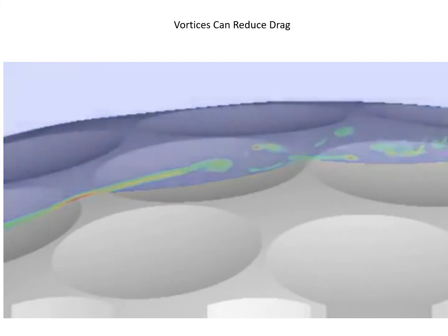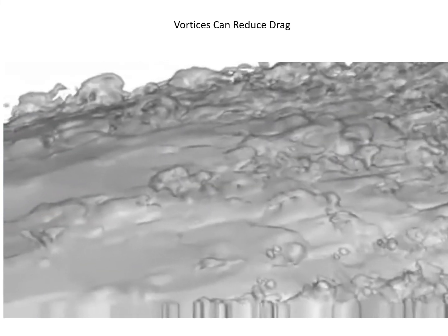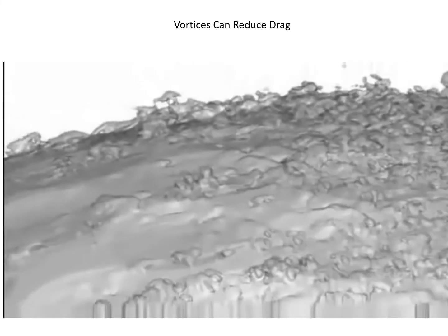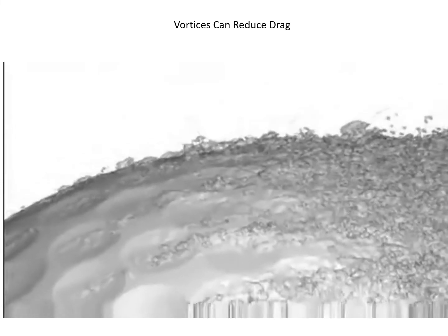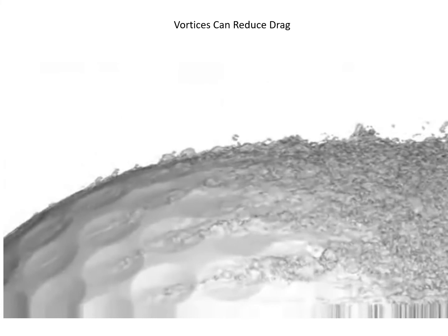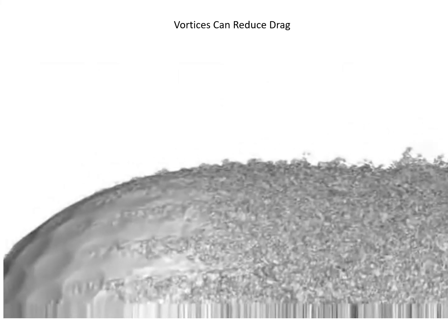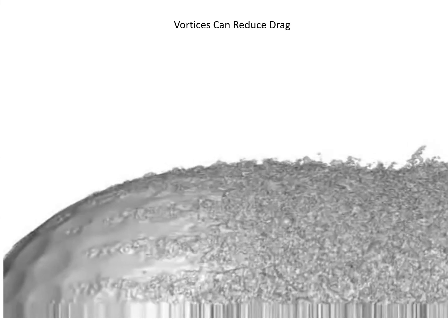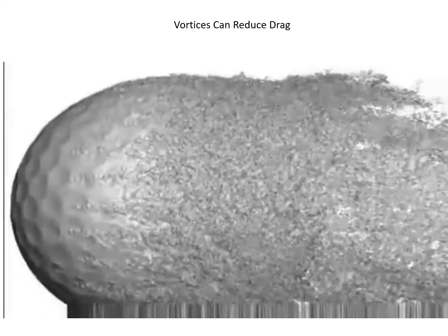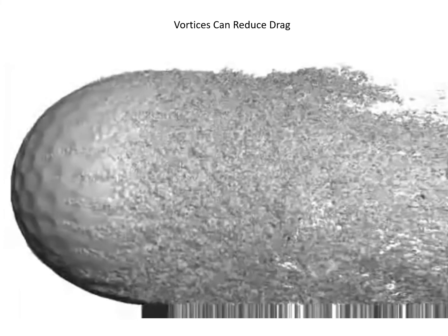We see that the cumulative effect of the vortices pulls air down onto the ball, delaying energy-wasting separation. Golf balls with dimples turn out to be almost twice as slippery as those without. But how many dimples should there be? How deep? What shape? Since there are no rules regulating these factors, sporting goods companies are free to tee up new patterns. But detailed numerical visual analysis, like we see here, will no doubt play a big part in golf ball design from now on. For LiveScience.com, I'm Dave Brody.